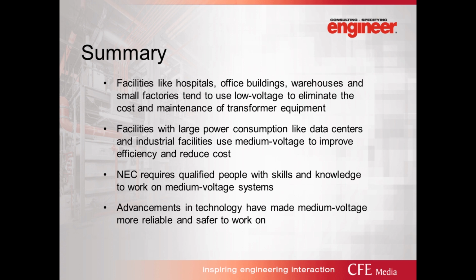From NEC, the NEC does still require qualified people with skills to work on that equipment. If you work on medium voltage equipment, they have to be trained for that, and that can be an issue. We did have a project where, when we were trying to decide with the client whether they wanted to go medium voltage or low voltage generators, the facility's concern was they could find a person to work on a 480 volt generator relatively quickly, probably 40 people within 20 miles of the facility, whereas if they try to find a medium voltage qualified person, it may take longer. There may only be 1 or 2 in the area. So for them, having medium voltage generators was an issue about just the people that can work on it. So it is something to think about.